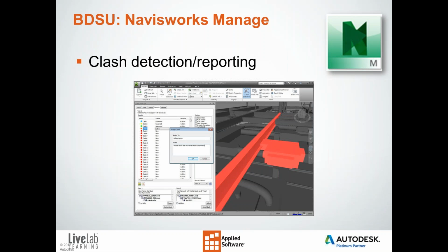Then I can move between clashes that result in maintain orientation in the model. I can create hard, clearance, and duplicate clash tests to support multiple coordination scenarios. And I can even analyze the space and time by linking clash tests to simulation and other animation.